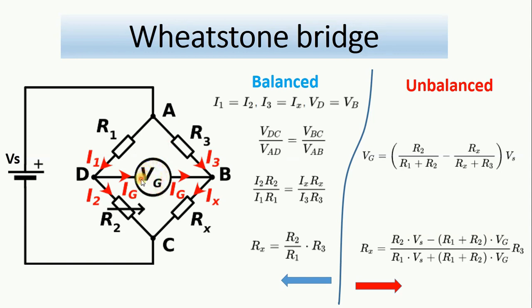Or if I have here an ammeter and I can measure a very small current in the ammeter, then it means that I can also calibrate my ammeter and remove this offset, or the measurement error, from my ammeter. So it is actually used to calibrate the voltmeter and the ammeter when it is in the balanced condition.